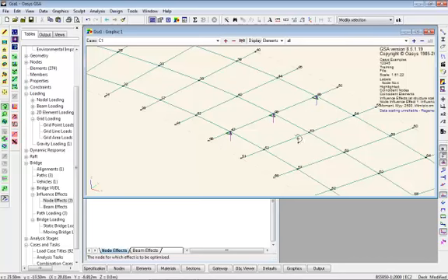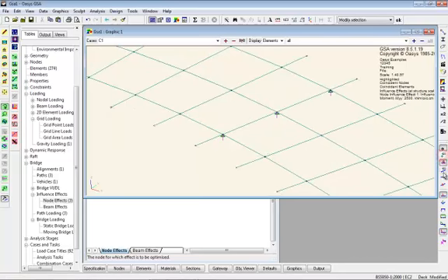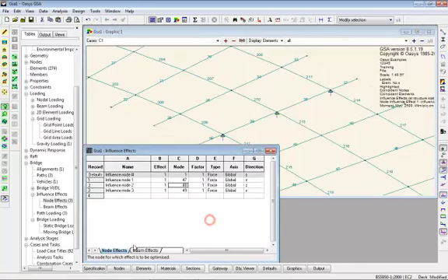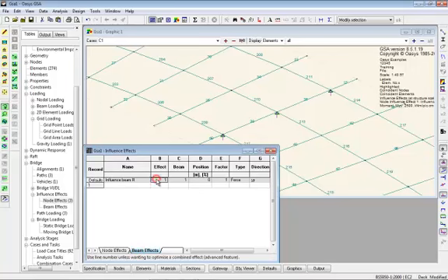Now I also want hogging moment on that line, which means I'll take the ends of these 3 beams here. So I'll do a beam effects, new effect group. So it will check the maximum hogging and maximum reaction separately.